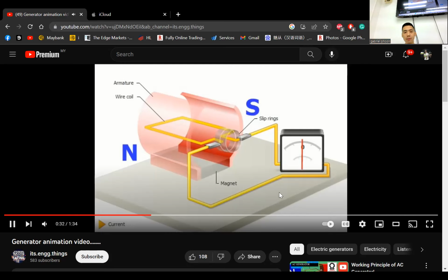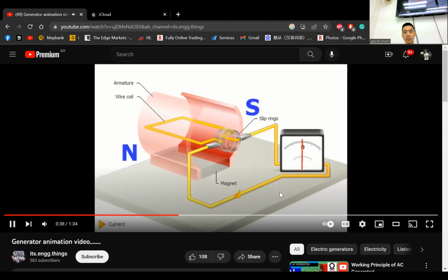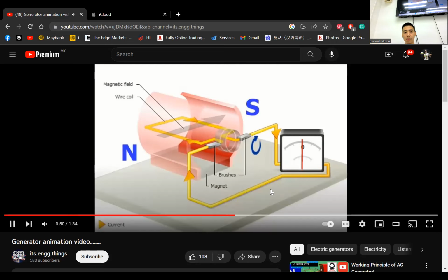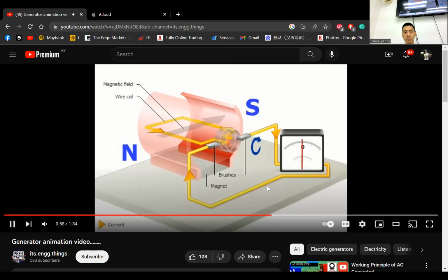The movement of the coil through the field causes an electric current to flow in the wires. When wires in the coil cut through the magnetic field between the poles of the magnet, current is induced in the wire. When the coil is turning in the direction shown, current flows toward the right in the far side of the coil and toward the left in the near side. The current flows through the wire in one direction during 1/2 of the turn. As it does so, the current changes from 0 to...